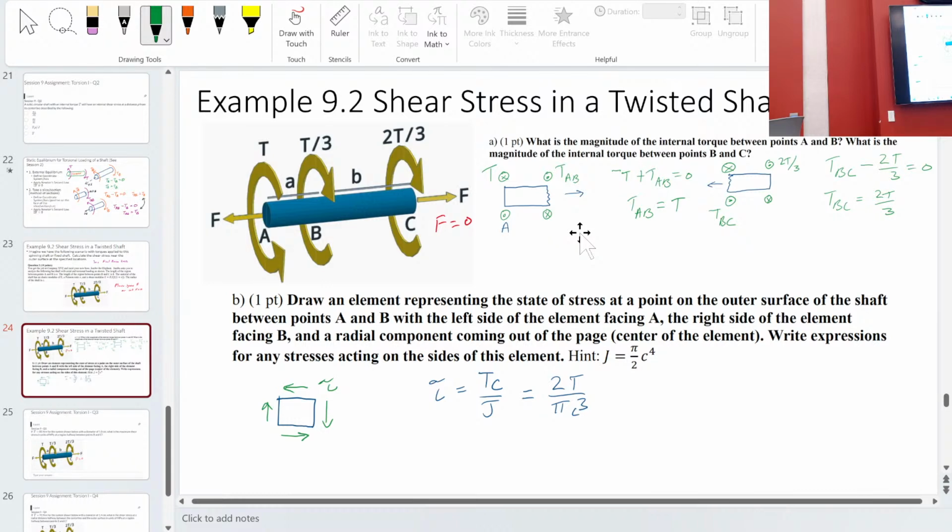and we're going to make the rigid body. We're going to use it on a surface. It's going to be this surface. We'll make that vertical. What is that? Okay, now what we're going to do is define the load. Take a load, we're going to use it on reference point 1. And now that's what we're going to put in my load. So essentially that's going to be the one direction.